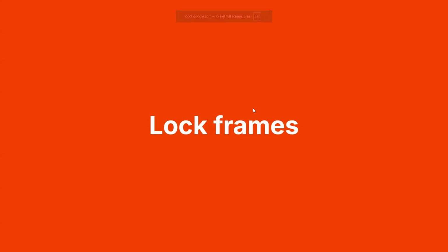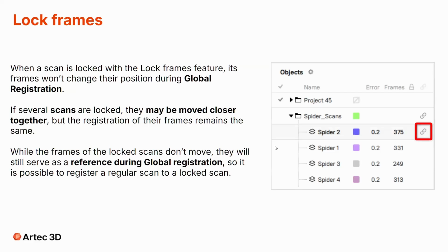Okay, with that introduction out of the way, let's get into the specifics. The first feature we're going to master today is lock frames. The next portion of this webinar will be dedicated entirely to this tool. We'll explore exactly how it stabilizes your data during registration and look at specific scenarios, like complex handheld scanning with the Spider 2 or Leo, where pinning your internal geometry becomes the key to a perfect final mesh.